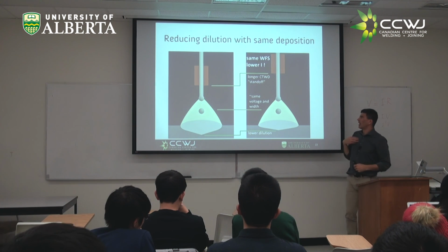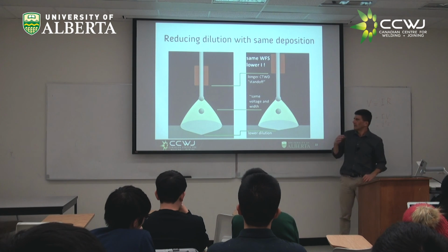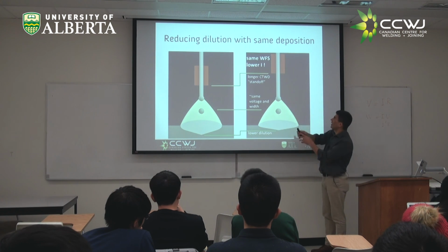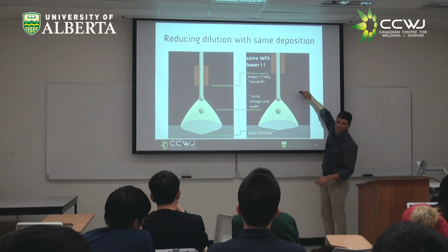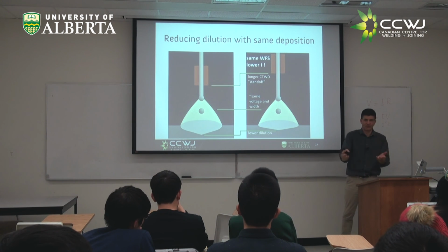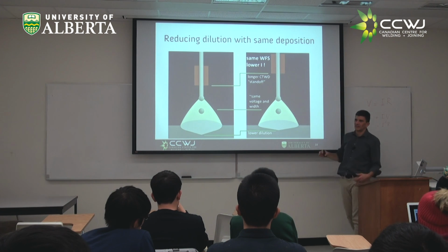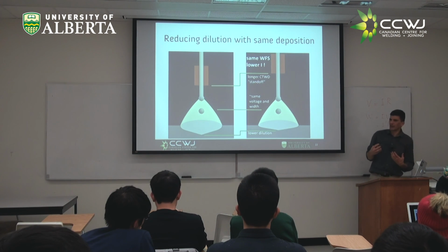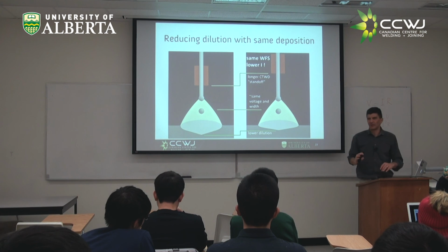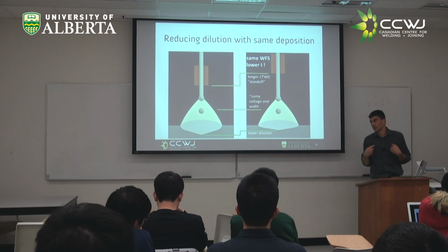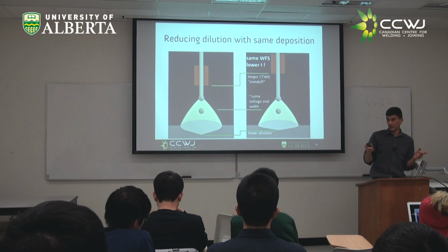The way I look at this, which is not exact, I tend to think there is close to zero voltage drop in the stickout. Of course, it's not, but I tend to think all the voltage drop happens in the arc. That's the way I look at it. It's not exact, but at least it takes me to the right places. And I also know the formulas to do it right, formulas that you also have.